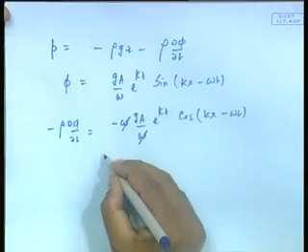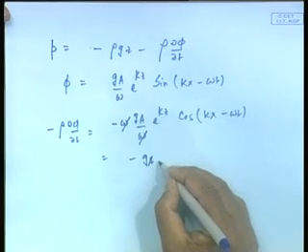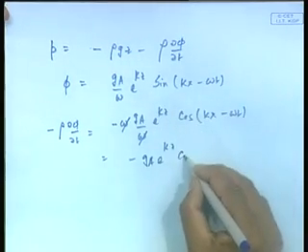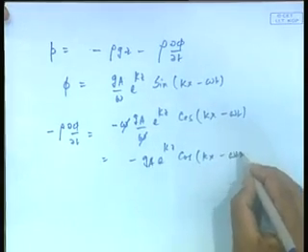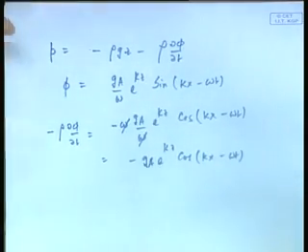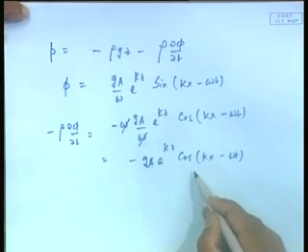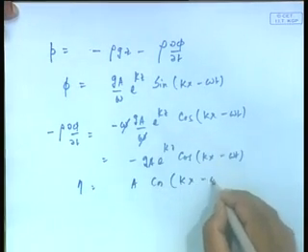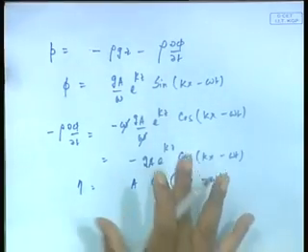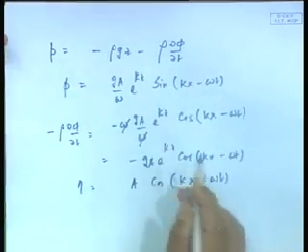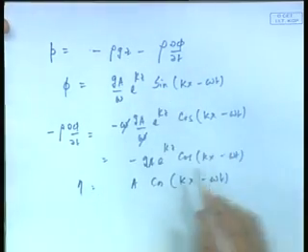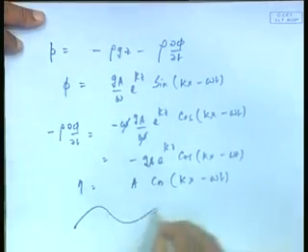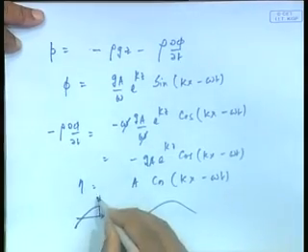So, that means it is minus g a e power of k z, cos k x minus omega t, etc. Now, what is happening? Obviously, you can understand this, that if I see this eta, it is something like a cos k x minus omega t. So, naturally there is a highest dynamic pressure, either positive or negative, that occurs under crest or trough for this. But remember, in all this formula, my z is 0 here.